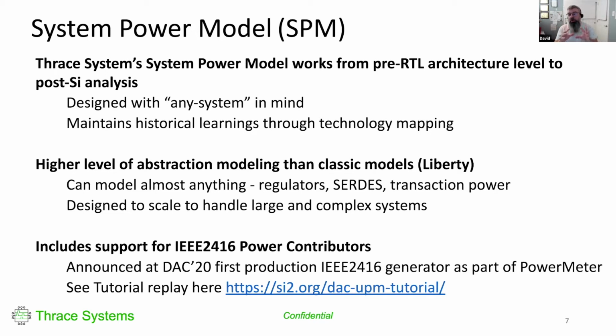We also recognize that in certain cases some learnings from previous technologies would need to be carried over. So for that, we have a method to map technology which would allow early power review of chips to be entered into the system. Our model has a much higher level of abstraction than what Liberty has, which is the classical chip level model. Liberty cannot model many of the complex IPs. We can. We can model the regulators. We can model SerDes. We can model transaction power.